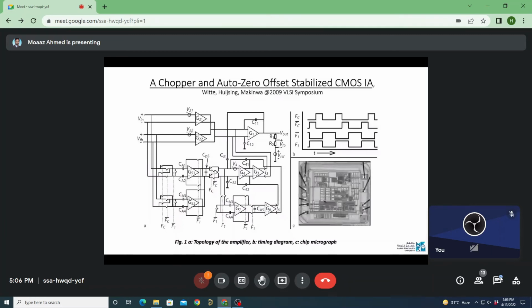So this is essentially a current feedback instrumentation amplifier. So what does current feedback do? It has two sets of transconductors, G21 and G22. G21 sees the input. You see V in, the input voltage, like the sensor's output, directly connected to G21. It has its offset V21. Then there is a feedback transconductor G22, which has a certain offset, of course, V22.